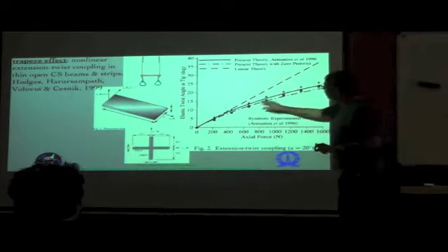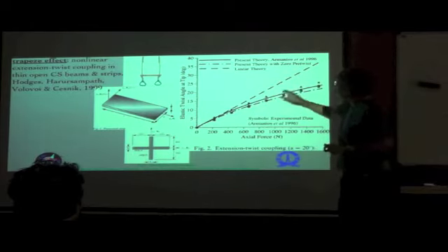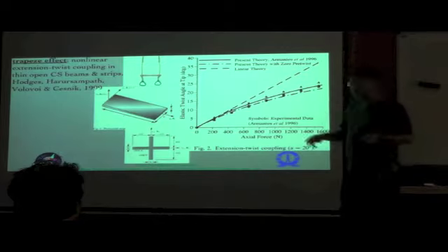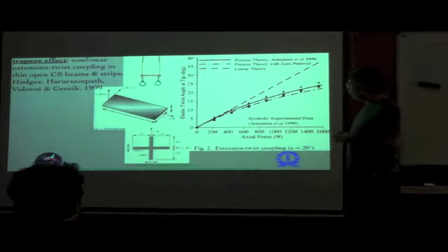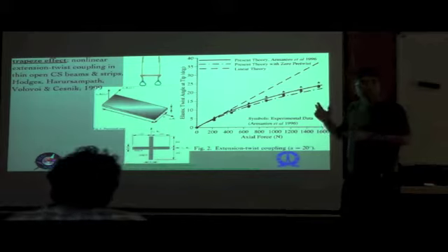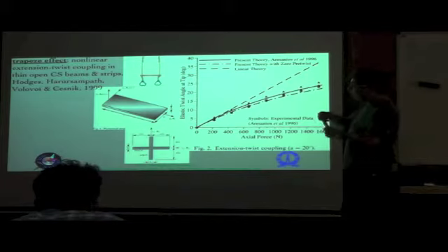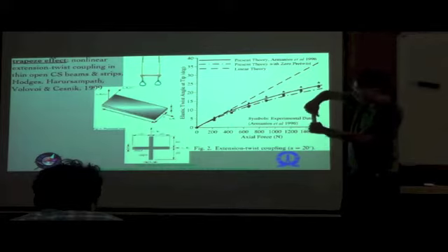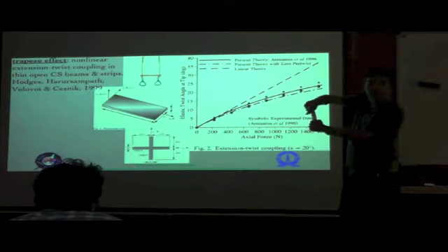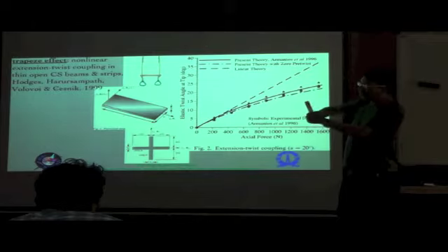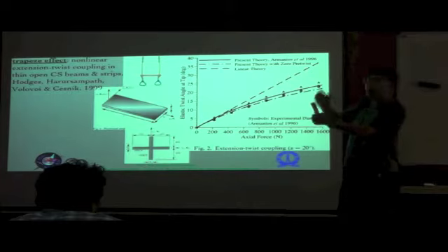There are some experimental results which are shown by these circles, squares and triangles over here, all performed on the same kind of layup, which is basically an anti-symmetric layup. For that anti-symmetric layup, we are exerting a tensile load using a UTS machine, for example, but allowing the ends to rotate with respect to each other and being able to measure those twist angles between the two ends, and therefore get the twist per unit length along the length of the beam.